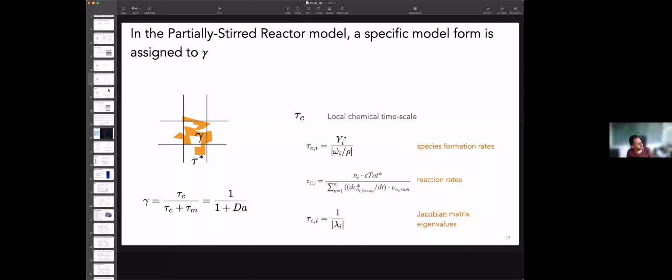At the same time, I also see your point, and there is more and more evidence that with an appropriate grid in the LES context, the importance of the subgrid model becomes less relevant. I think one criterion would be to look at the local Taylor number at the scale of the grid that you are resolving. This would be a good indication whether your grid is fine enough. But it's not something you can know a priori, so it's a bit complicated. But I agree that it's a question whether this correction is needed. For the sake of generality, it is important, in particular in the perspective of having fuels with very different behaviors.